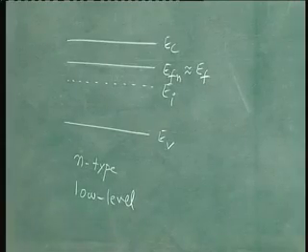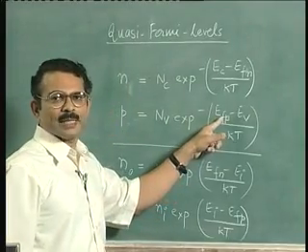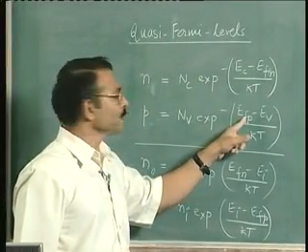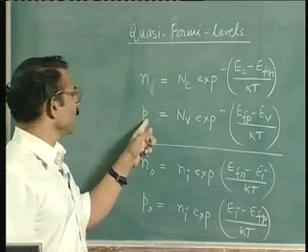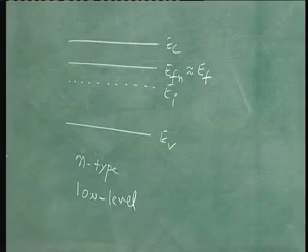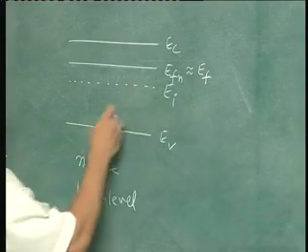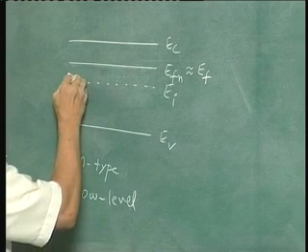However, the quasi-Fermi level for holes cannot be the same as under equilibrium, because even if it is low injection level, the minority carrier concentration is always disturbed. That is what we saw. So EFp will be closer to the valence band edge. It depends on how much your excess carrier concentration is.